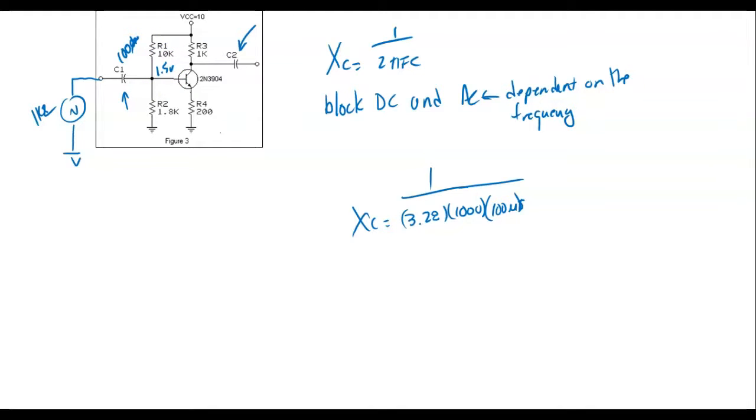So that 1.5 volts is there, and when I bring in an AC signal, this allows the AC signal to go through. It doesn't let the DC get out, but it brings the AC in. Then the AC is going to subtract from the 1.5 volts or add to the 1.5 volts, like DC sources in series. If this is 1 volt peak to peak, then on the positive alternation this would go up to 2 volts, and on the negative alternation it would go down to 1 volt.